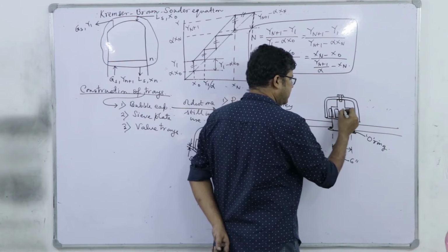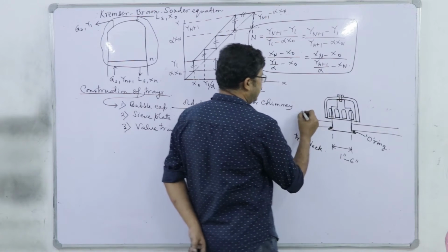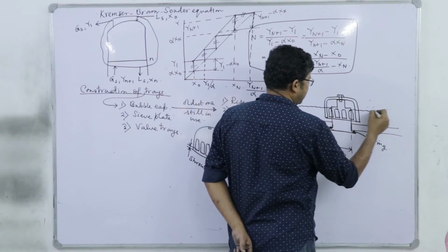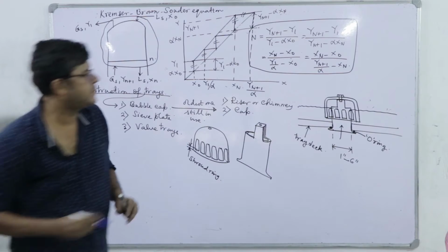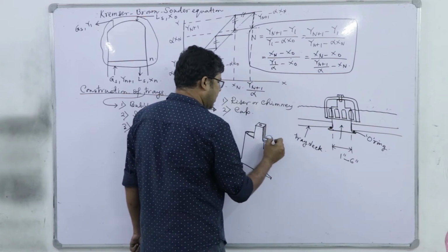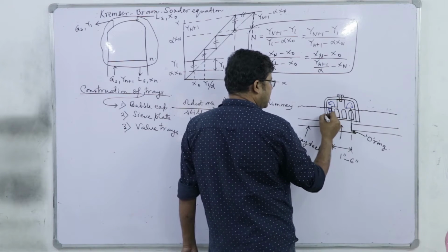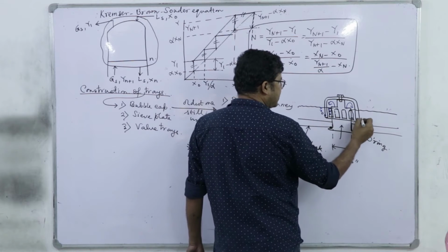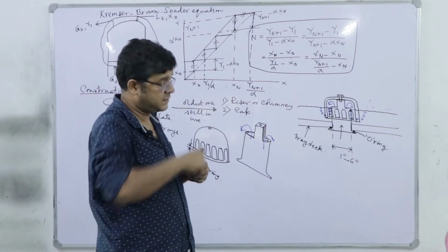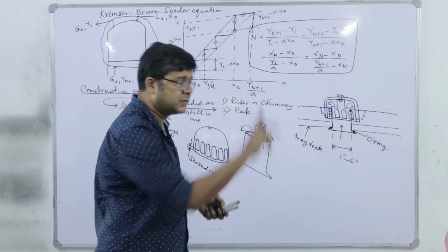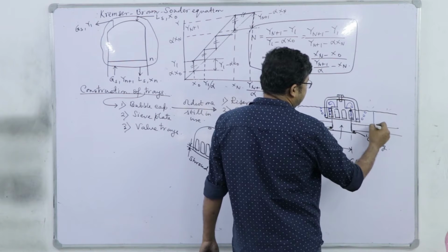It's not exactly the section, but for understanding I am drawing it like this, and the liquid, you see, will fill up the space like this. Now the gas will move through the chimney and it will move out, right, here it will move out. It has to form bubbles and the bubbles will pass like this. Through this residence time it will exchange. First it will move down and find the slot, and through the slot opening it will again move up through the pool of the liquid, which is the hydraulic depth we have to maintain here. There is a liquid pool height.